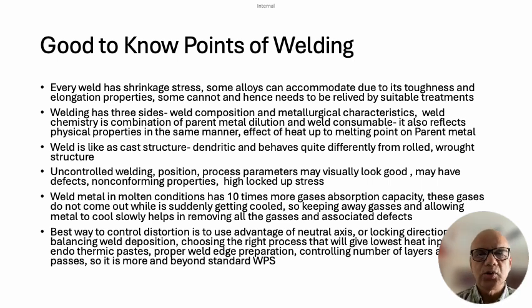Otherwise, you'll have to really do testing to understand the behavior and the material characterization. So weld chemistry is very, very important to know. It is not the chemistry of the electrodes or the consumables. It is the chemistry of the resultant dilution, which is going to come from the parent metal and the consumables we are using, and the process in which we are using them.